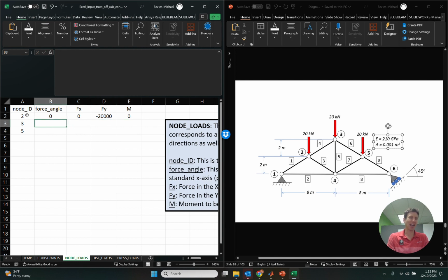Similarly, it does the exact same thing as what we have above. Let's assume that I have negative 90 rotation for my force angle, and then I applied 20,000 newtons. What does that mean? It means, let's assume that you have originally the x direction there, and then you rotate it 90 degrees clockwise. That's a negative 90. And now the x direction is pointed down, so we have 20 kilonewtons pointing down. Same thing as what we had before.